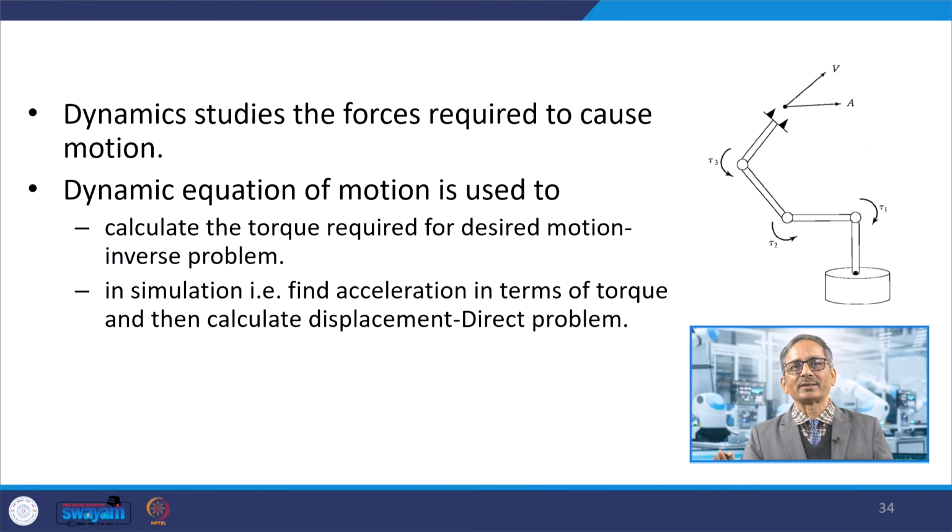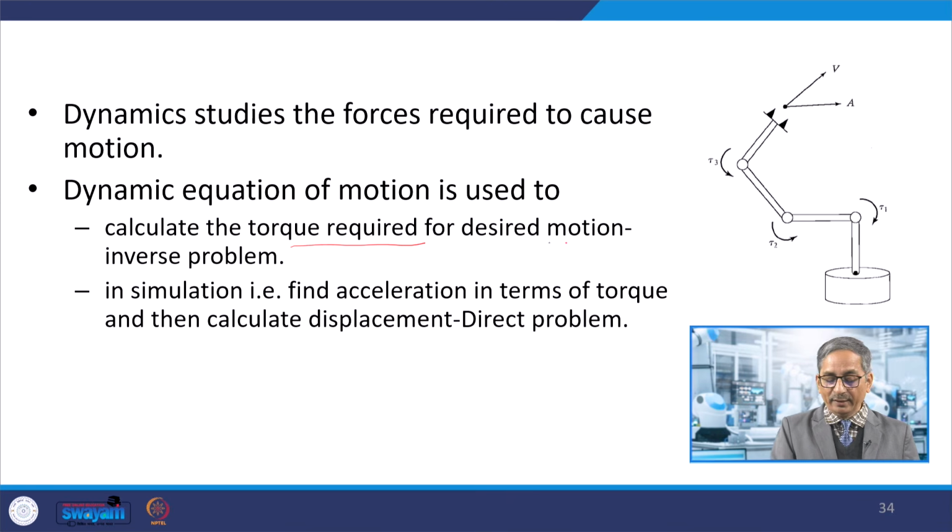So, dynamics studies the forces required to cause the motion. Now, there could be two applications for that. One application is that we calculate the torque required for the desired motion, which we call the inverse problem. The other, the direct problem, is that we find acceleration in terms of the torque and then calculate the displacement. So these are the two types of study we do in dynamics.